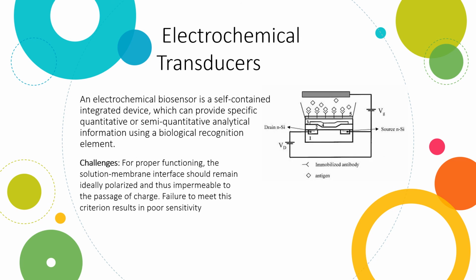For electrochemical transducers, they're described as a self-contained integrated device which can provide specific quantitative or semi-quantitative analytical information using a biological recognition element. Some challenges with these transducers are that for proper functioning, the solution membrane interface should remain ideally polarized and thus impermeable to the passage of charge. Failure to meet this will result in poor sensitivity.